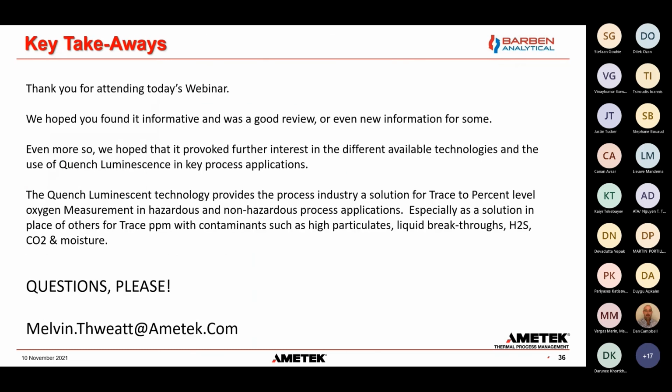So thank you for attending today's webinar. We hope you found it informative. It was a good review, or even new information for some. Even more so, we hoped it provoked further interest in the different available technologies and the use of quench luminescence in key process applications. The quench luminescent technology provides the process industry a solution for trace to percent level oxygen measurement in hazardous and non-hazardous process applications, especially as a solution in place of others for trace ppm with contaminants such as high particulates, liquid breakthroughs, H2S, CO2, and moisture.